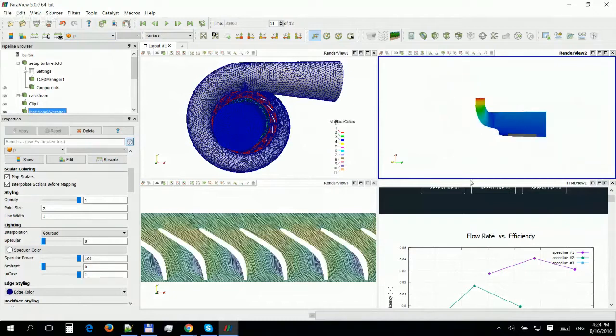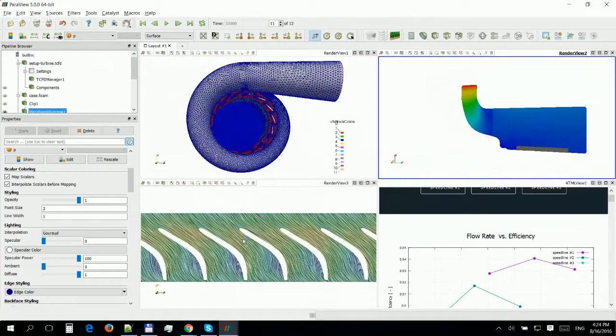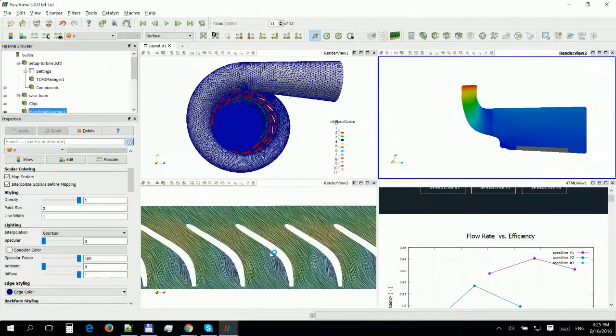That's quite important. Also what you can do is a blade to blade view at any level between hub and shroud, and you can transform your Cartesian vectors to the view where you can see any level between hub and shroud, and of course relative velocities and vectors. Maybe I should stop here.